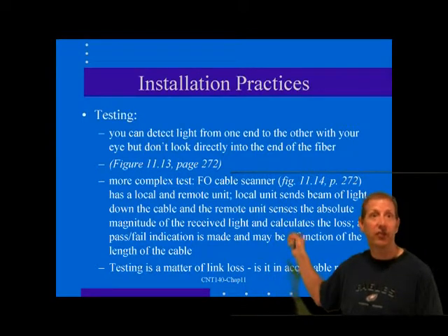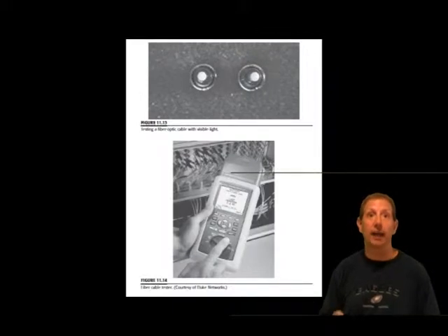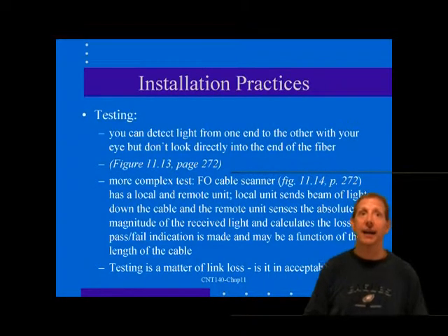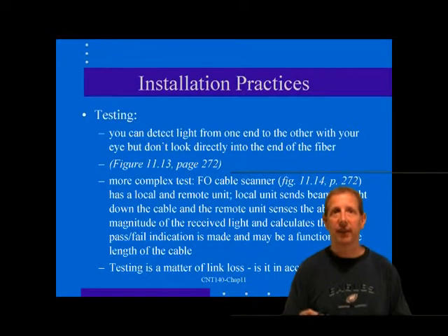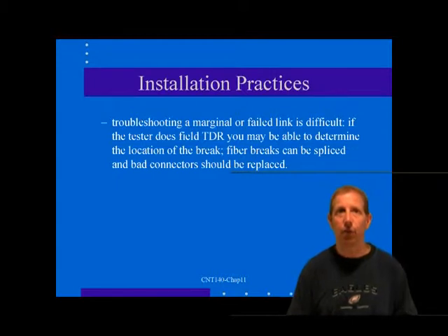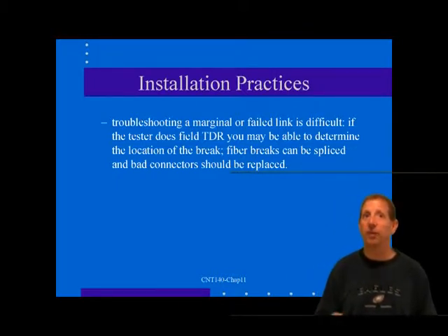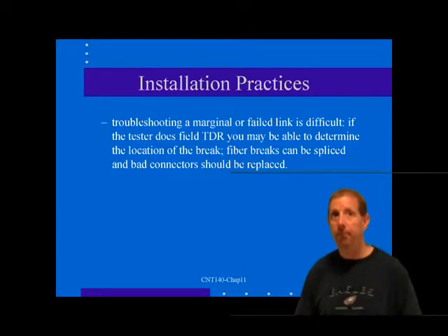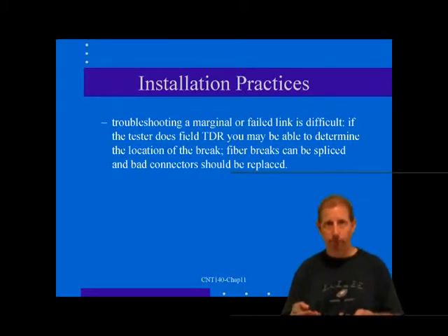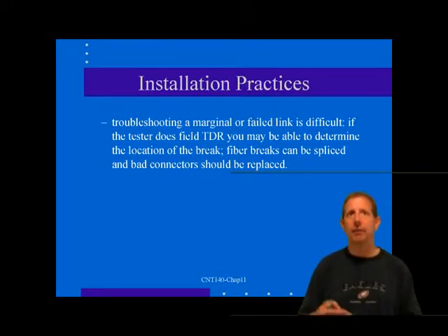In some cases, the scanner may be an adapter module that is used with a copper cable scanner. However, because copper scanning is inherently more complex and expensive, and because different cable crews may be involved in installing fiber optic cables, you may want to purchase a separate fiber optic tester. Now, all fiber optic cable testers for field use have a local and remote unit.